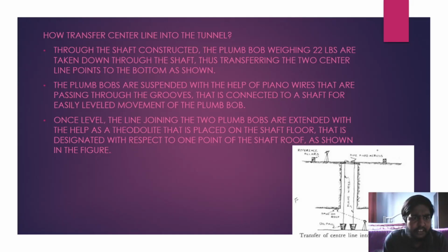Initially, the reduced level of the top mark is determined with respect to a benchmark, for example a point near the mouth of the shaft, and later the reduced level of the second mark is also determined. With all the measurements, a benchmark is determined at a point on the tunnel side wall, and lastly, based on this benchmark, the floor levels are transferred and the measurements continue.